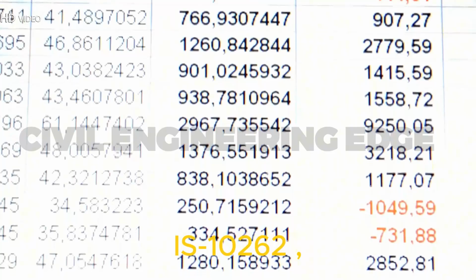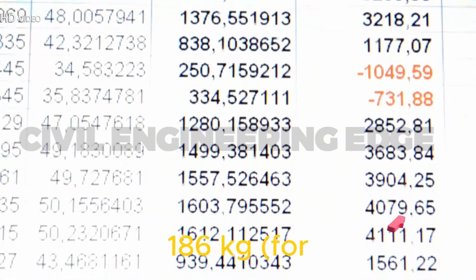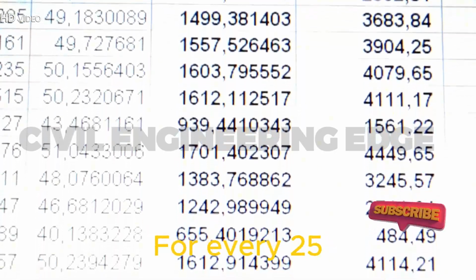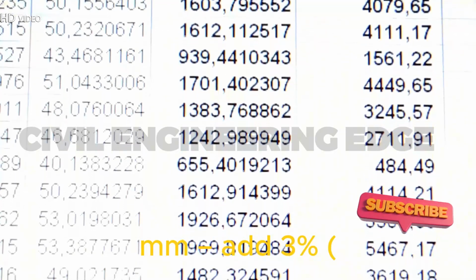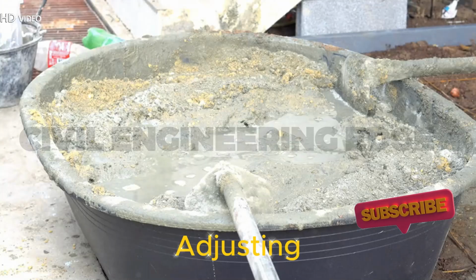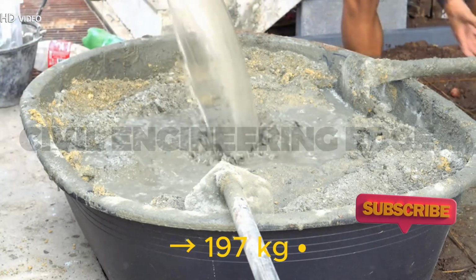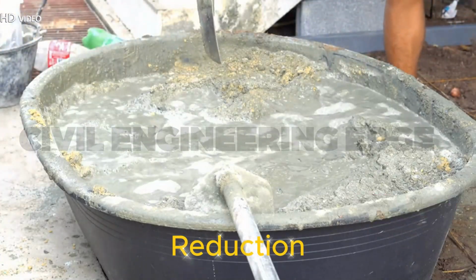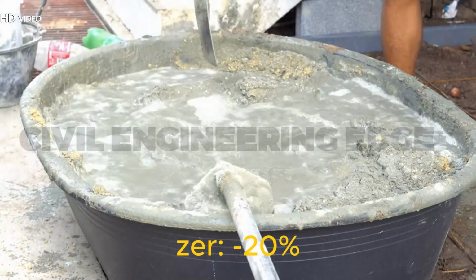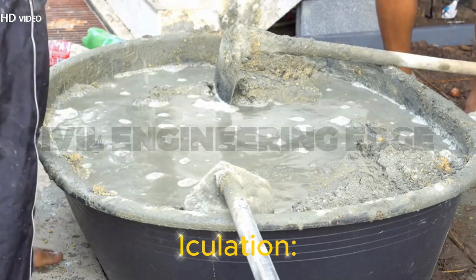3. Water content calculation. IS 10262, Table 4. For 20 millimeters aggregate, 186 kilograms for 50 millimeters slump. Adjusting for 100 millimeters slump, plus 6% gives 197 kilograms. Reduction due to super plasticizer, minus 20% gives 157.6 kilograms.